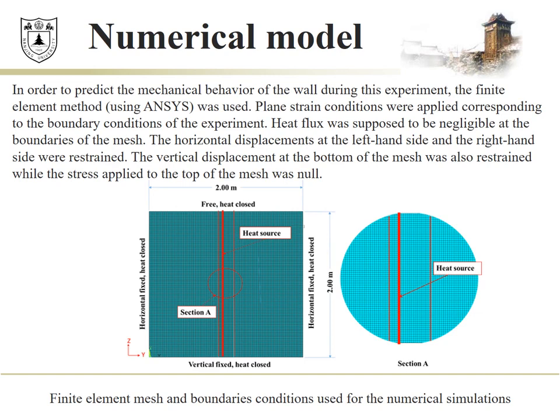In order to simulate the heating phase performed in the experiment, the temperature of the pipes was imposed. The initial temperature of the whole system was first fixed at 10 degrees. To start the heating phase, the temperature of the pipes was increased from 10 degrees to 48.5 degrees during the first 20 hours.